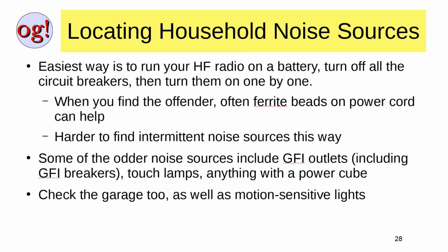Now, a way to locate household noise sources. The easiest way is to run your HF radio on a battery. Turn off all the circuit breakers and then turn them on one by one. When you find the offender, find whatever on that circuit is the offender. Often ferrite beads on the power cords can help.